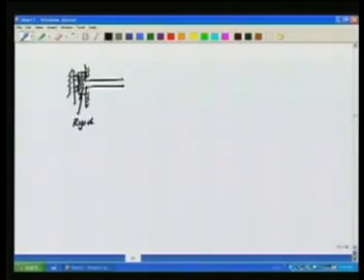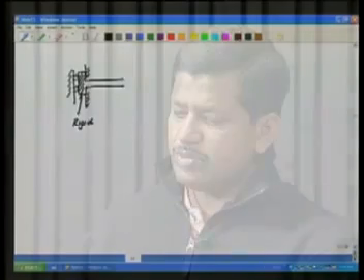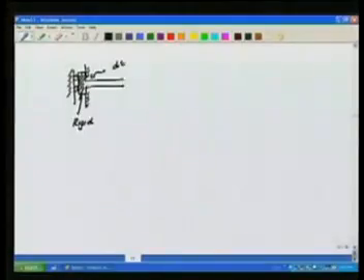So the rigid support is moving in a guided slot. So what happens, because of this, I have dV/dx at x naught equal to 0. It is not allowed to bend. Okay, but I could certainly at the same time specify a shear force V naught. So we have the various types of boundary conditions.